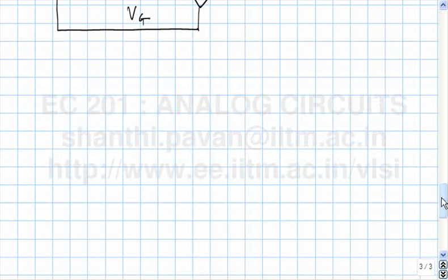So that kind of finishes the discussion on the CMOS inverter. So far we have seen NMOS transistors, we have seen PMOS transistors, we have seen how to put those two together, and putting the two together is very advantageous because the NMOS and PMOS transistors are complementary in some sense. You can do nice things like have an active load where you can get a very large gain without having a large resistor, or you can have a CMOS inverter which gives you in principle a very large gain without any additional bias network at all.